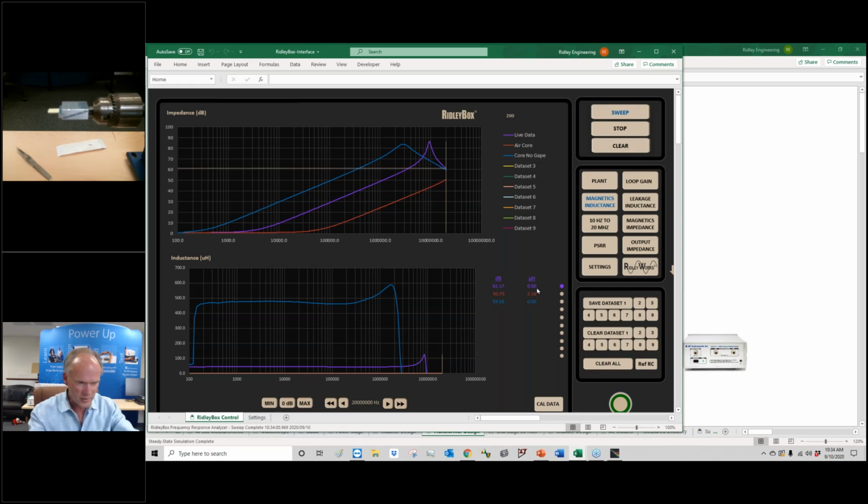You can buy core clips for these, but if you put a metal core clip next to a gap, it's going to get hot. So we don't clip them. And people don't tend to use the clips in production either, because it's easy to break the core when you use a clip. Plus it creates a conductor between primary and secondary. You just got metal where you don't want metal. So people use epoxy, they can use tape, they can use all kinds of constructions for making these transformers work.